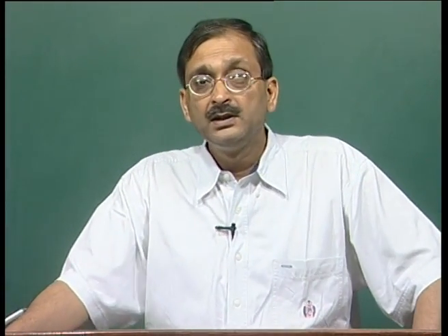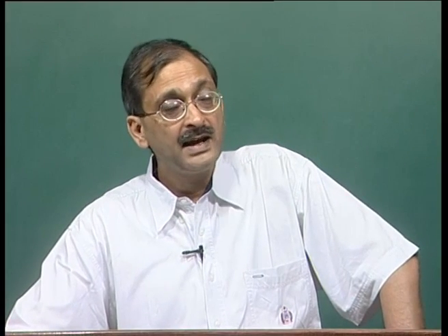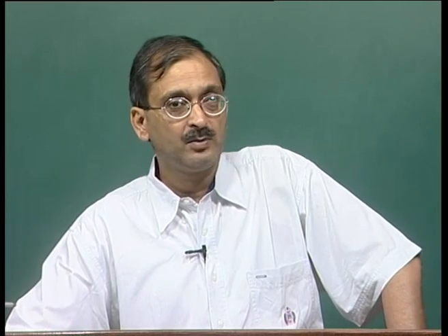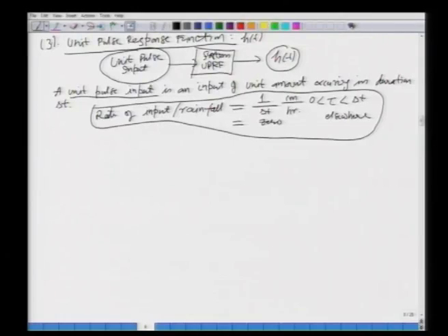Now, knowing the first two functions, that is your unit impulse response function u and the unit step response function g, okay, how can we find this function h, which is your unit pulse response function, all right. So, what we will do is we will take the earlier functions and then apply our linear system theory, proportionality, superposition and so on, okay. Once we do that, we should be able to find out what is this h, all right. So, let us look at that first.